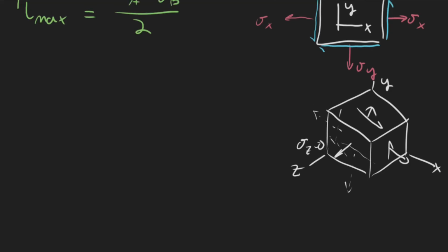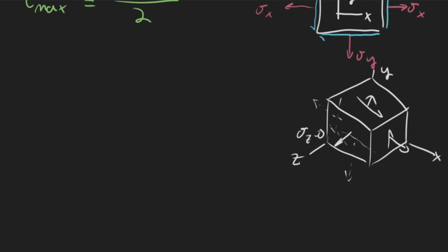And so the sign convention, at least for this class, is to label the 3 normal principal stresses, which are the maximum stresses on that axis. So if you imagine I've got my x face right here, no matter how I rotate it, the maximum stress that I'm going to get on that face is one of the principal stresses, and then I'll also have one for the y face and the z face.